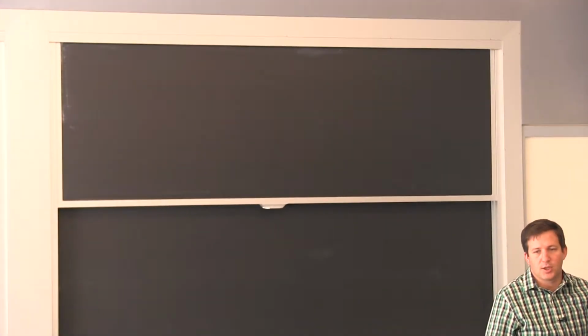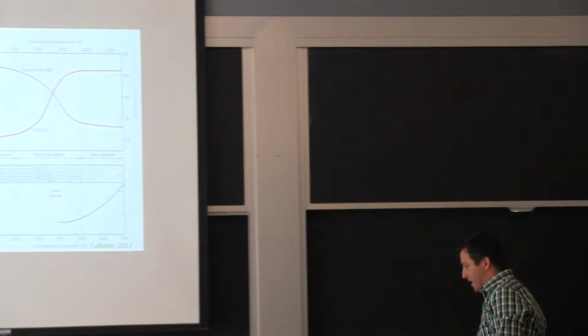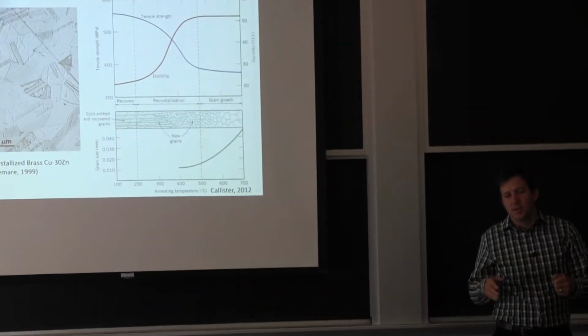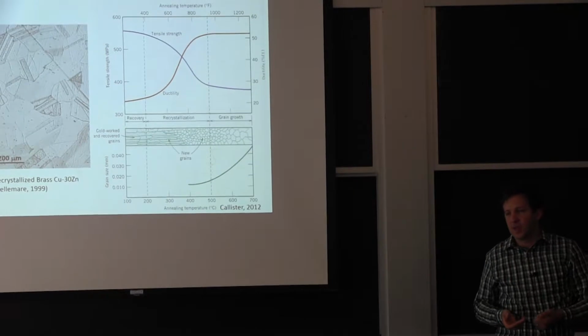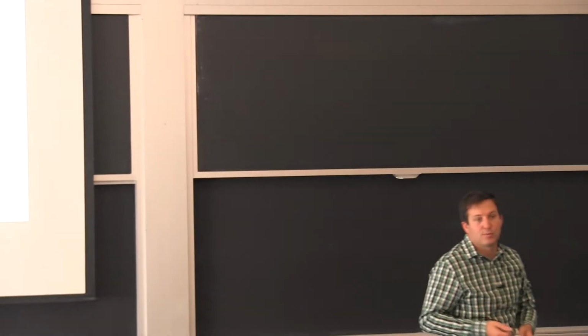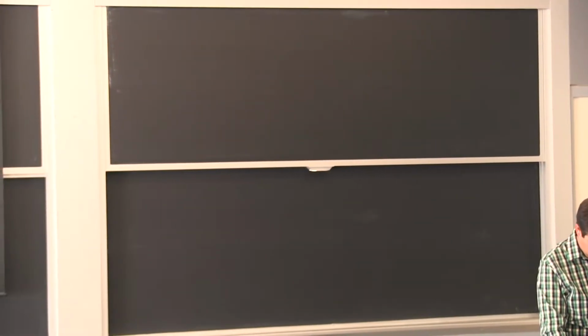So when we're talking about 100 micrometers for this type of alloy, it makes sense that when I deform it, I don't really see the roughness. When we were looking at those copper samples yesterday and we were seeing all that orange peel effect, it's because the grains were bigger than 200 micrometers approximately.